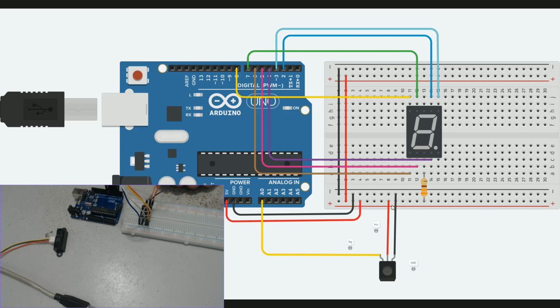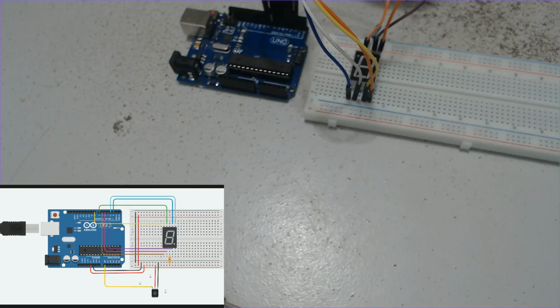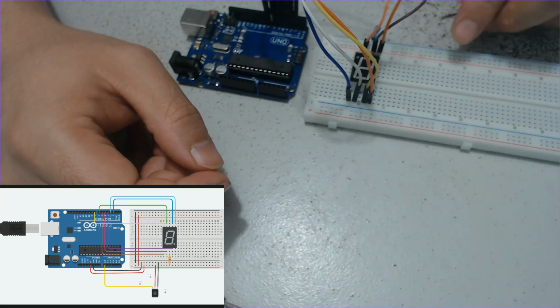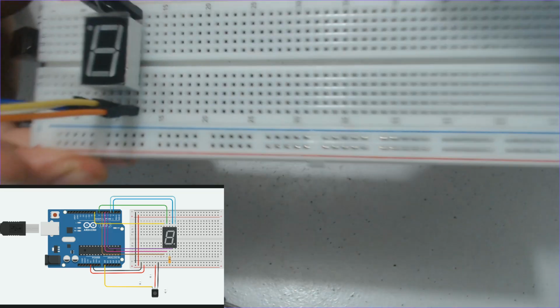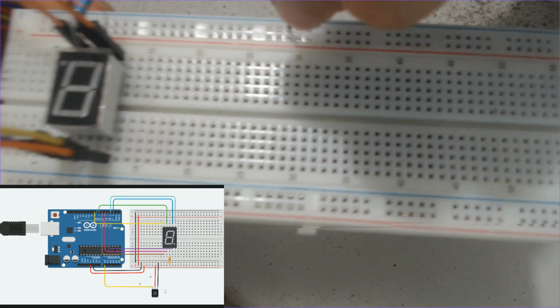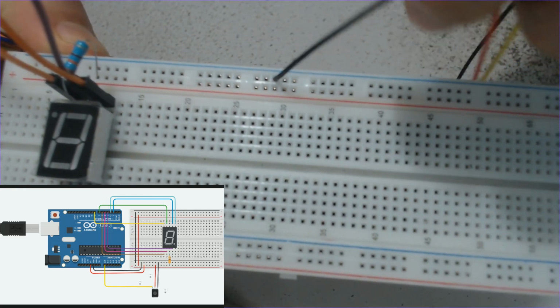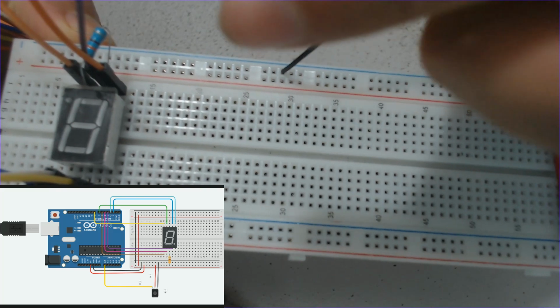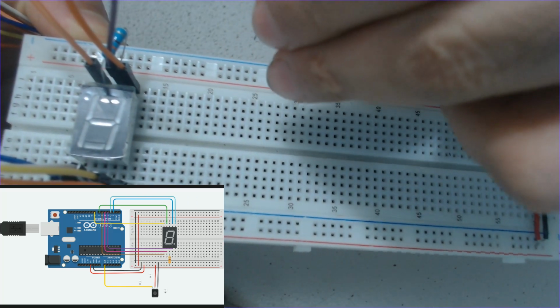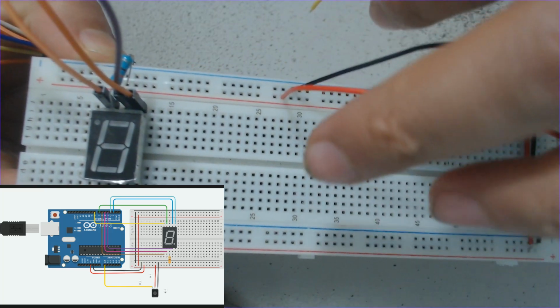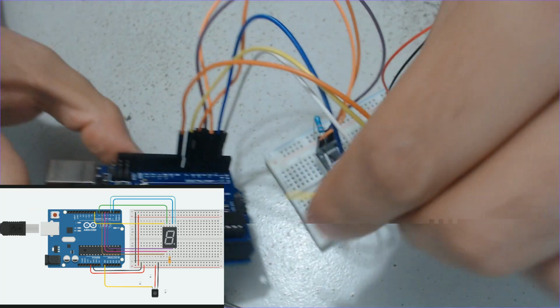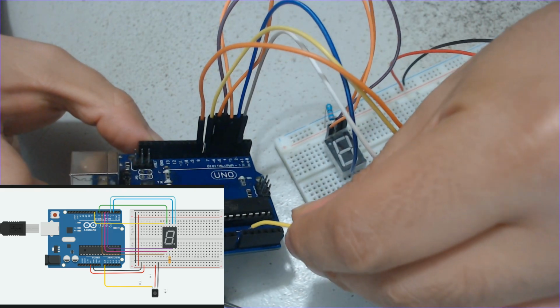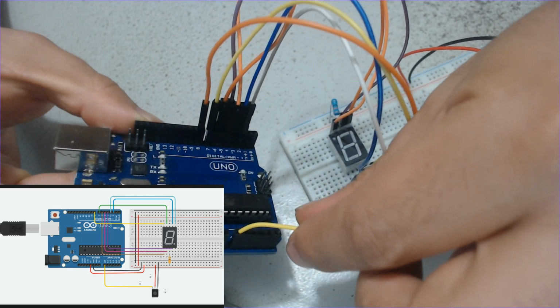We may be able to connect this directly to the positive and the negative in the Arduino, no, my bad, in the breadboard. So the black one goes to negative, to the blue connections, the red one goes to the red line, and this yellow we may be able to connect directly to port A0 here in the Arduino card.